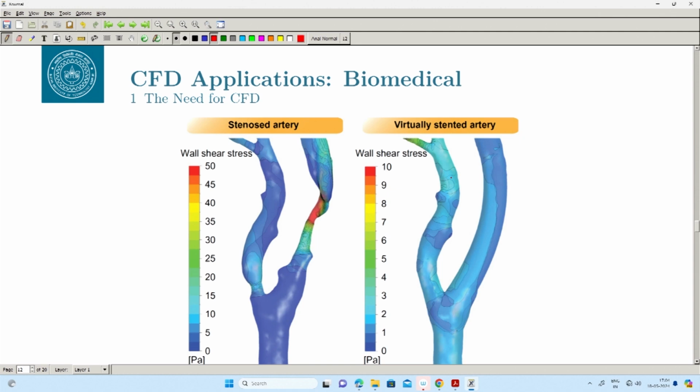First of all, of course, before you do any CFD, you have to validate with a truth model, whether it is coming from an experiment or from real data. That validation is necessary for any CFD application, right. That has to be done, and once you are satisfied with that validation and you think your model is working, for example in the human model, let us say you want to simulate the blood flow. Blood is a non-Newtonian fluid, it is not like air. So, the constitutive relation is different in the case of blood compared to a Newtonian fluid.